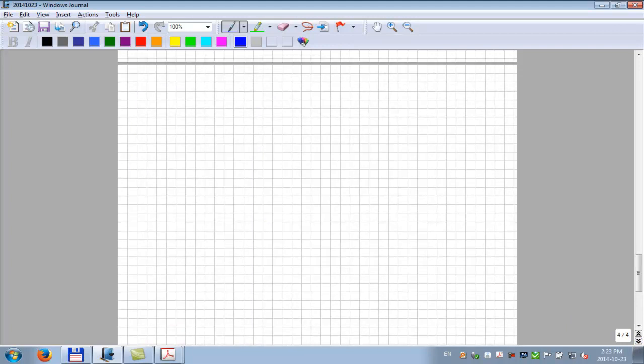Okay, so let's get started with the first topic, and that's going to be our reservoir gas rate equation. And that's going to be relating the gas rate with bottom hole flowing pressure at the current average reservoir pressure or at the current boundary outer pressure.